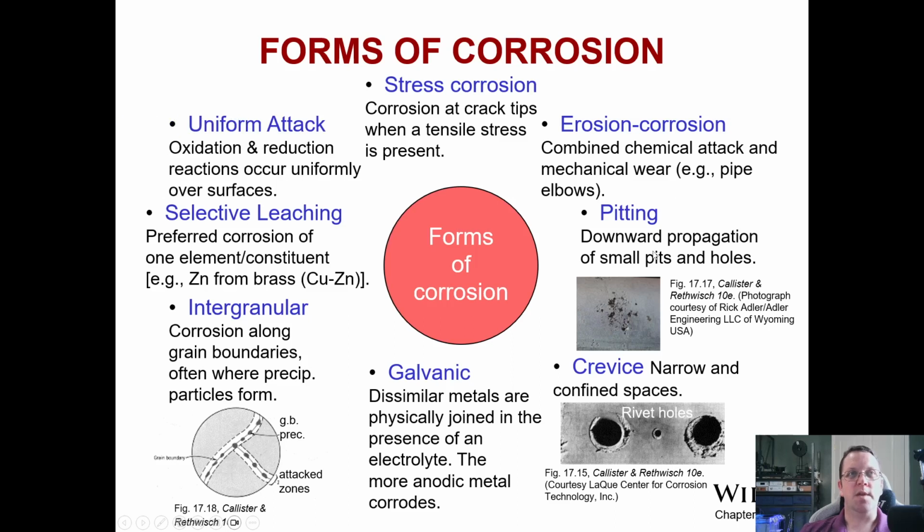There's also selective leaching. It does happen. It's kind of an interesting process because we think of corrosion as being non-selective, but in fact it often is very selective, and it's driven based on the thermodynamic differences that we saw in the EMF table. If there's a difference in electromotive force, you always have something trying to cause corrosion going in a specific direction.